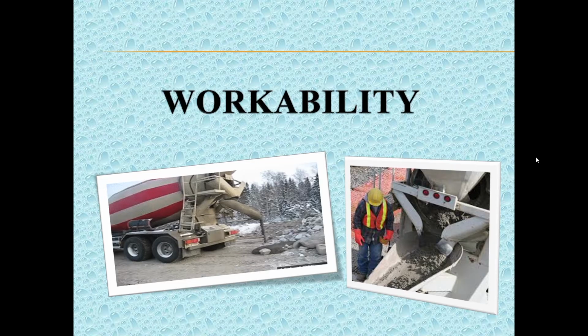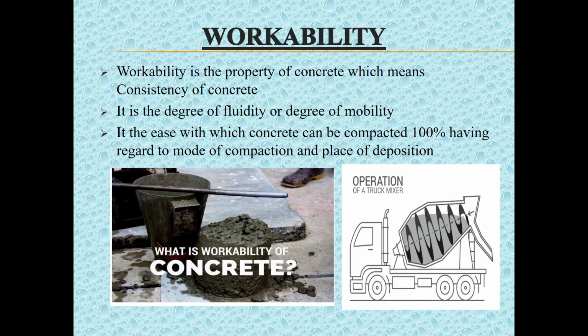We are going to see what workability is and how both are related to each other. Let us begin with what workability means. Workability is defined as the ease with which concrete can be compacted to 100%. 100% compaction contributes to the maximum strength of concrete. Lack of this 100% compaction leads to air voids, which reduces the strength and durability of the structures.